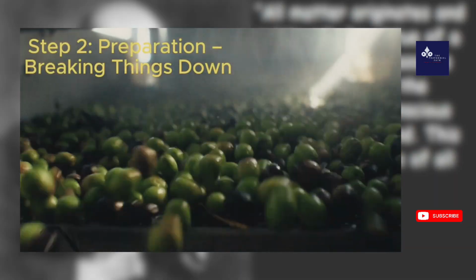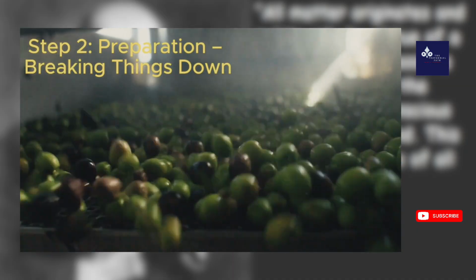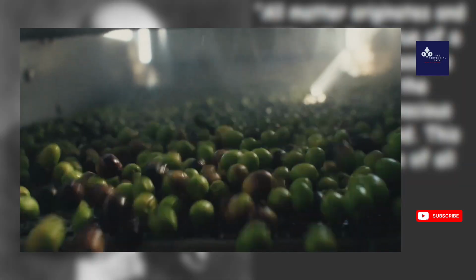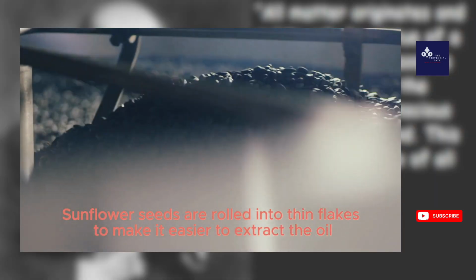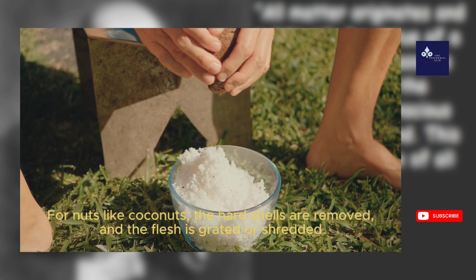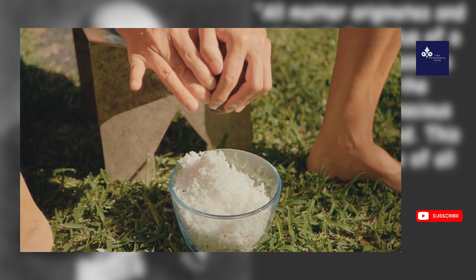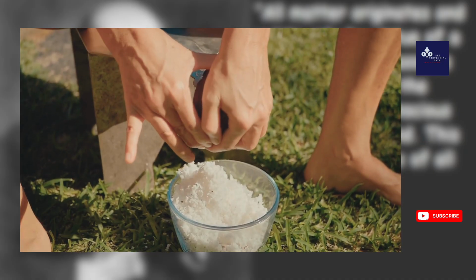Step 2. Preparation, breaking things down. Next, the seeds or fruits need to be prepared for oil extraction. This usually involves a combination of grinding, crushing, or flaking. For example, sunflower seeds are rolled into thin flakes to make it easier to extract the oil. For nuts like coconuts, the hard shells are removed and the flesh is grated or shredded. This step is all about increasing the surface area of the material so we can get as much oil as possible.